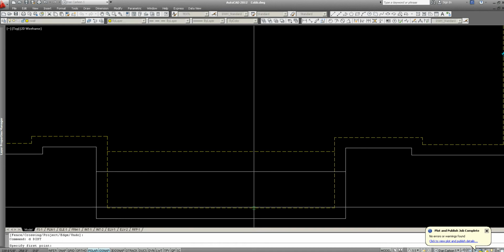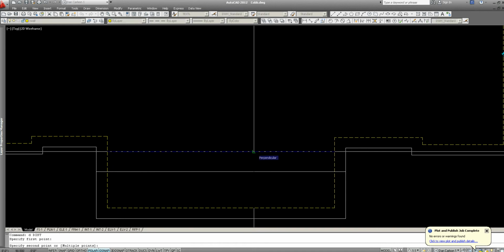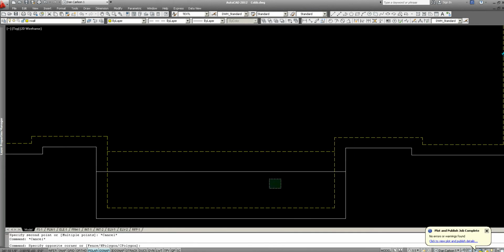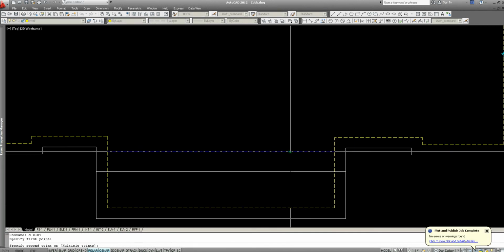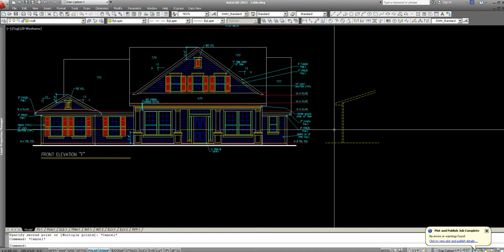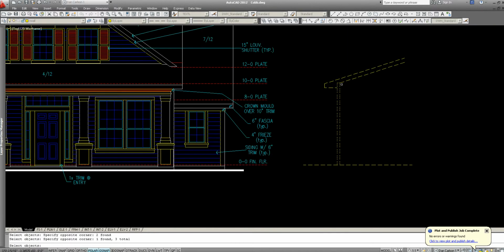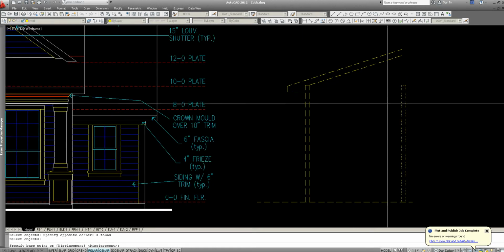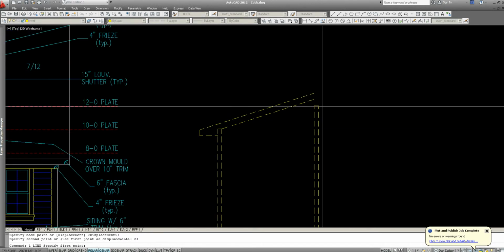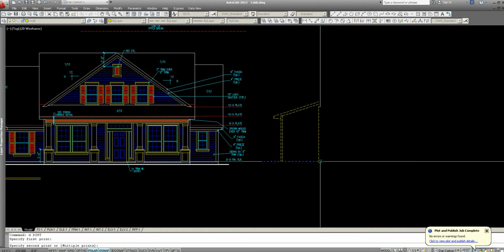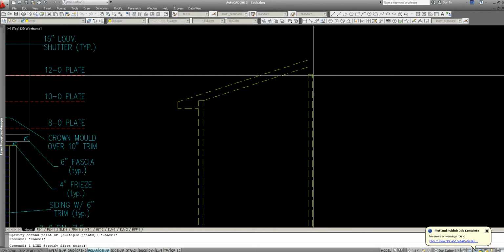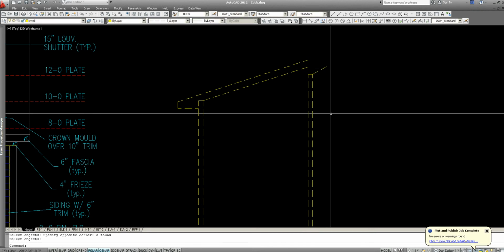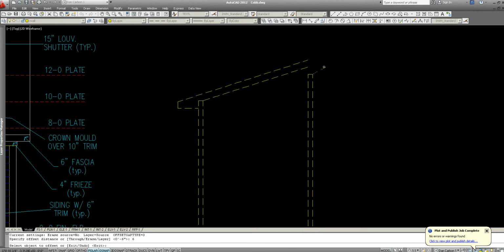This is the front wall of the porch. And they are 8 feet apart. You can see down here at the bottom corner of my screen when we do a distance command, 8 feet. So we come over here and copy this wall up over 8 feet. And we raise it up 24 more inches because now it's a 12-foot 1-inch wall. See, 12-1. And this we're going to give a 7-and-12 pitch. So 12, 7, close, erase, offset 6 inches.